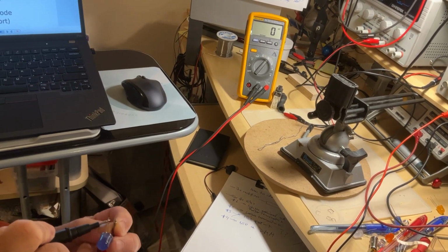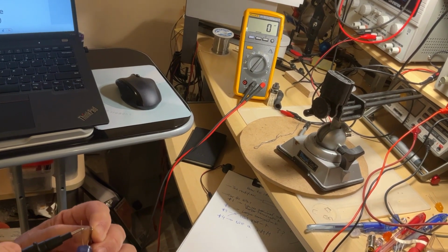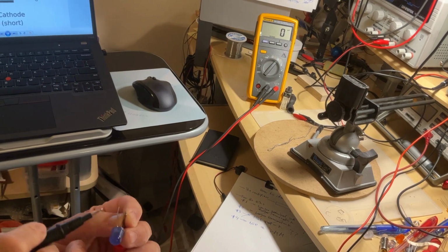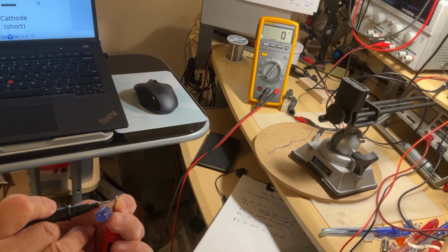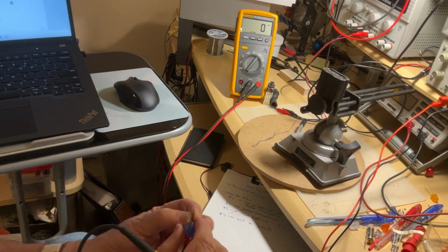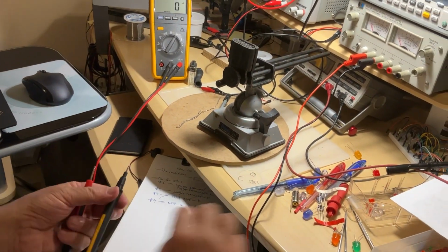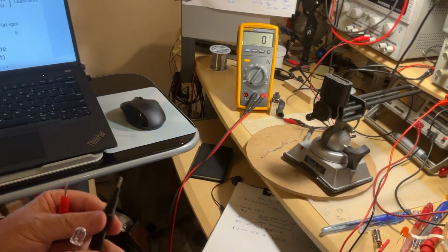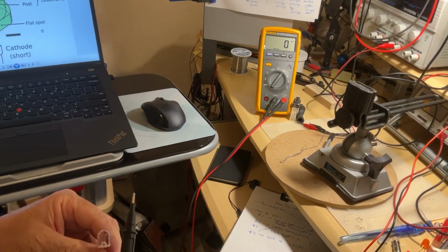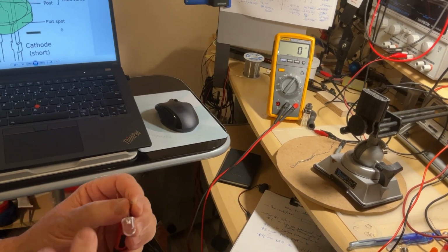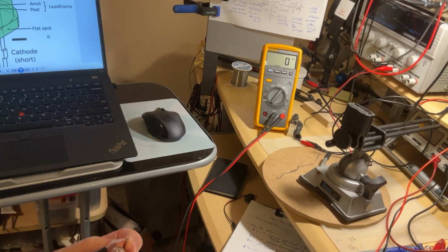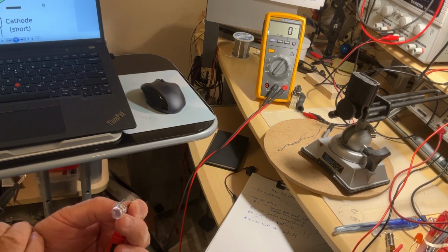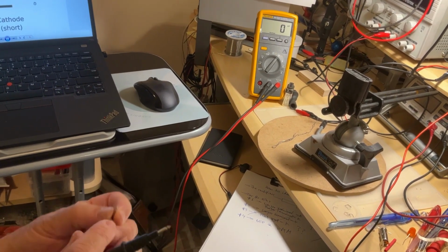You see on this one here? You won't be able to identify the light on the diode. You can barely see something, okay? Even very good quality meters like this one are having trouble to identify the anode and the cathode because that position for the diodes, again, it was actually designed for rectifiers, not for LEDs.